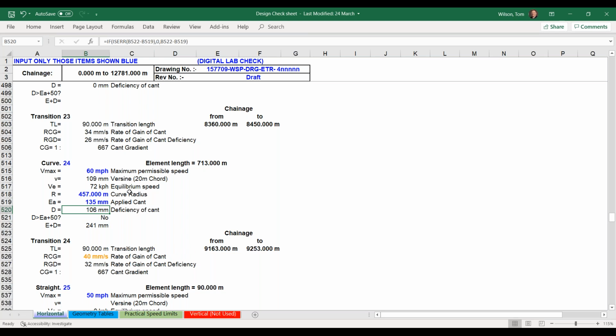is 55 millimeters a second, I can say, actually, I can increase the speed of trains around that curve from 50 up to 60 mile an hour, and that may shave 2 or 3 seconds, and you can calculate the whole thing. But on that one element, there I've got a 10 mile an hour increase. And that's quite a prize in track design. I haven't changed the radius of the curve. I've just put the cant up a bit.